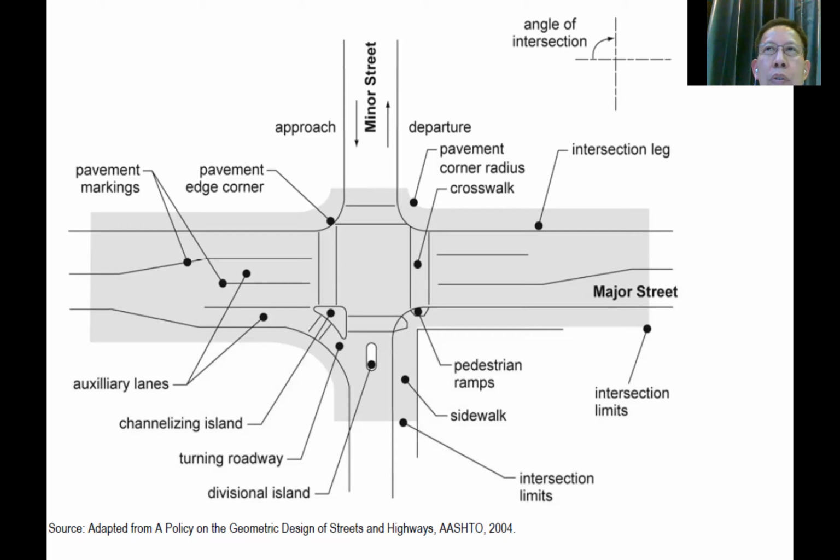But if you want to put some pavement markings right away, those pavement markings will melt and be very dirty after that, because the tires will pick up some of the color from the asphaltic concrete and then press it on the marking, so it's not going to be very clean. White or yellow is going to be very dark very soon, so it's not good to put the pavement marking right away.